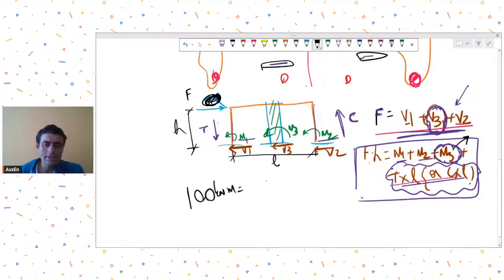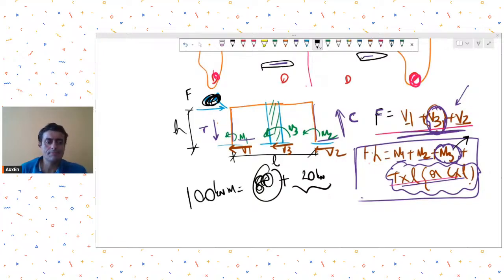Now out of this, 80 kilonewton meter is getting resisted by wall, and the balance 20. So how will you find out this 80? From your analysis results, you will get how much wall is resisting, and then the balance, you can say, is getting resisted by the columns in the form of axial tension compression couple.